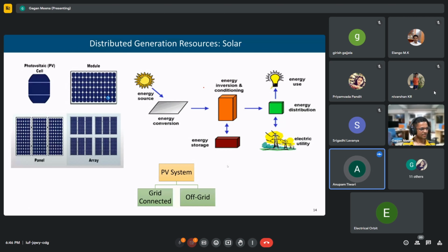My question is, as we know, a generator produces both active and reactive power, but solar cells only produce active power. From where will we get reactive power in the system from PV generation? Although the cell produces active power, because it produces DC and we have to interface it with the AC grid, there is an inverter in between. That inverter can provide reactive power.